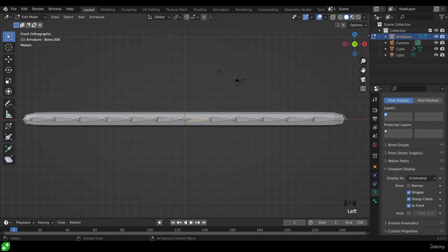In order to connect this bone to this bone, we select this bone first, so that's the one we want to connect, and then the one we want to connect to last. So that is the active object highlighted in yellow. And as usual, we press Ctrl P to parent. Now there's an option here to keep offset. That would actually connect them, but keep them a distance apart, whereas connected, if I press that, you'll see it actually moves and joins together.